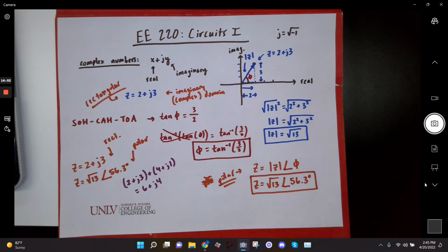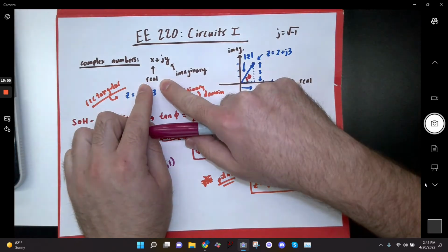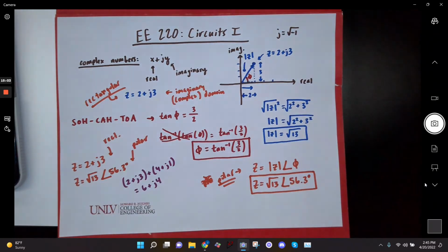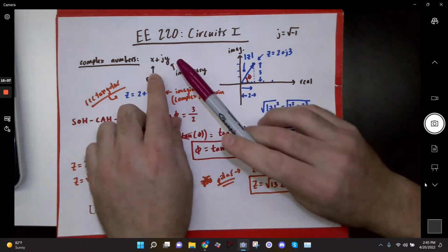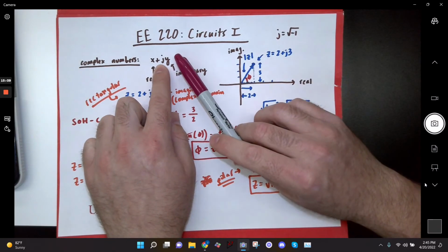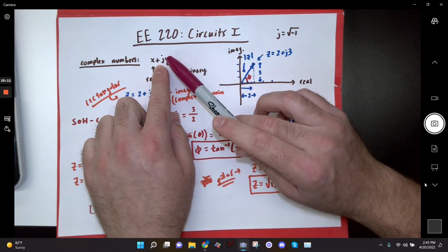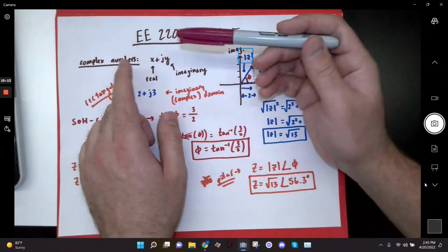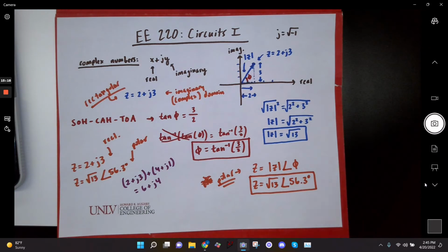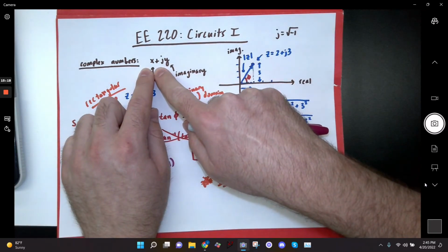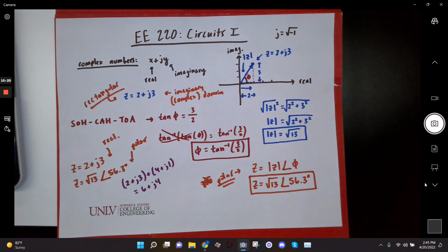Yeah? When you say imaginary, do you basically mean you can't visualize it in your head? You can visualize it in your head. It's a real impedance. But if I say real, now it seems like I'm talking about this. Right. It is an existent physical impedance that depends on frequency, and we are only representing it in this manner because now we know that this part of the rectangular complex number is the frequency dependent part, and this part is the non-frequency dependent part. It's literally just to segment it into parts and to keep everything organized.